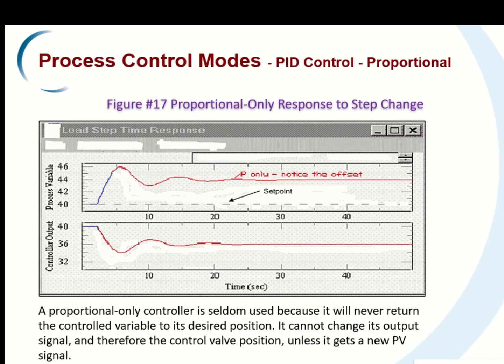This means that the proportional only controller does the job expected of it. So at least until a disturbance or load change happens, at the beginning the controller error is 0 and the controller variable is stable. The next process disturbance will cause the controller variable to change and the controller will act. Unfortunately, the system will recover back to a condition of stability but not with the control variable at the set point.